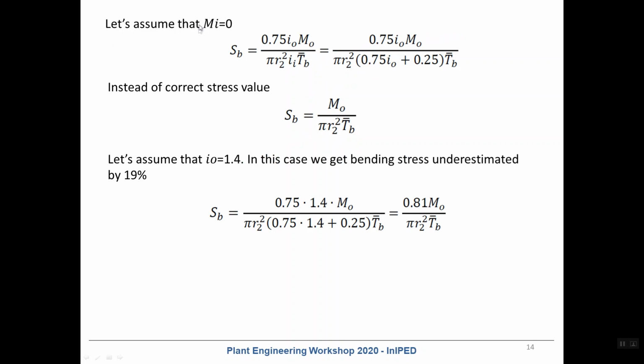If we assume that the in-plane bending moment is 0, and take the out-of-plane stress intensification factor equal to 1.4, we will underestimate the bending stress by 20%.